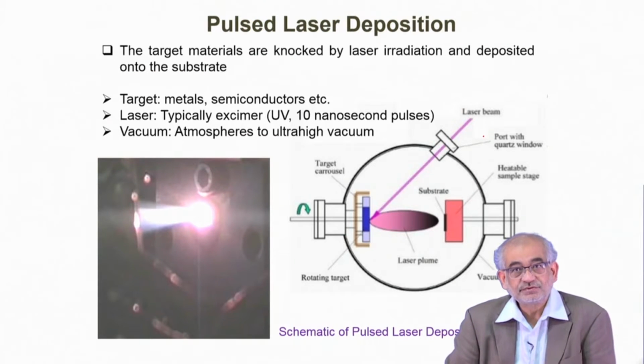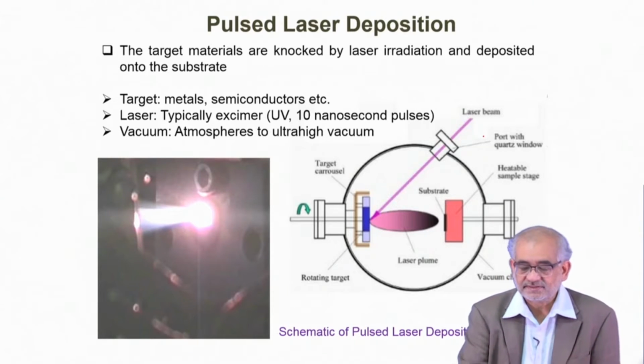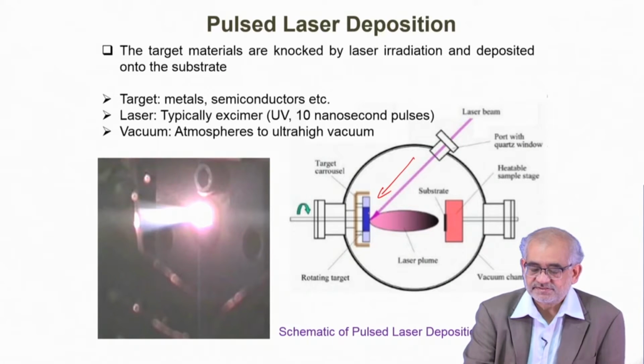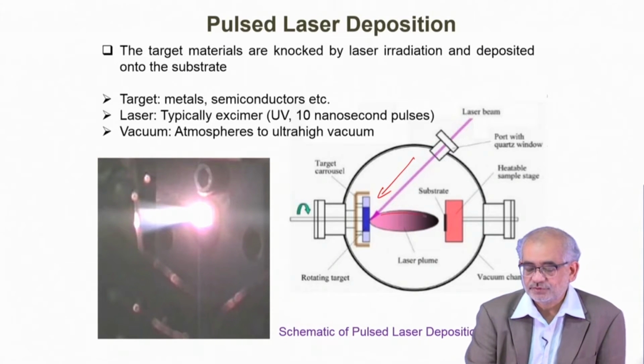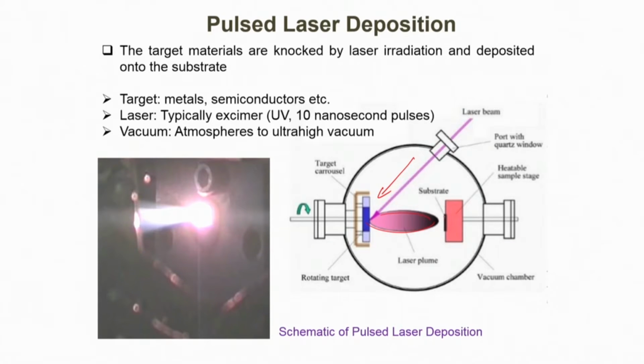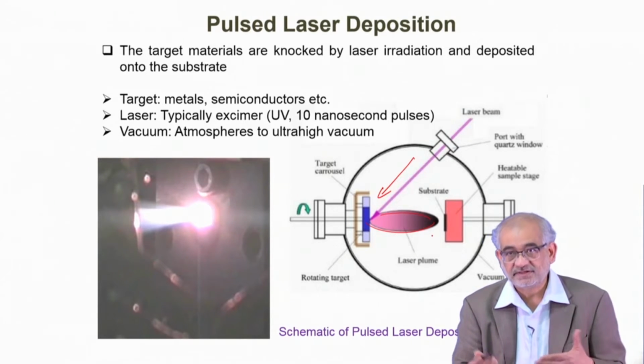Laser also allows you to make very thin films. That's the beauty of laser: instead of feeding powder or wire, you can have a target, and the high intensity beam will instantly create a small pool of vapor. That vapor creates a plume, and the plume gradually comes to a colder region where you have a substrate, on which you can form a layer. And the layer thickness can be extremely small, a few nanometers, a few tens of nanometers, even smaller, and you can precisely vary that.